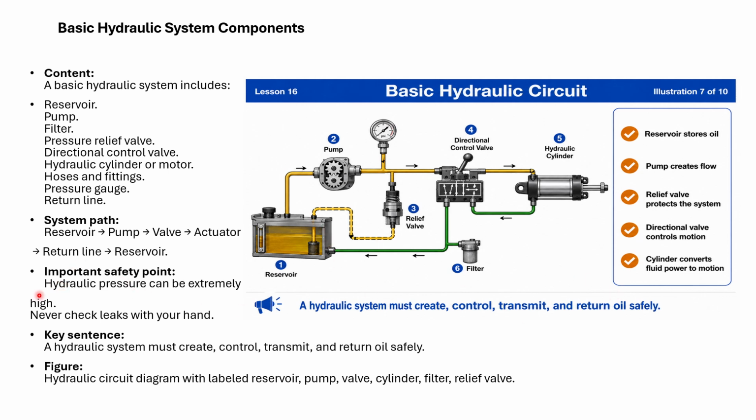Important point: hydraulic pressure can be extremely high. Never check leaks with your hand. Key sentence: a hydraulic system must create, control, transmit, and return oil safely.